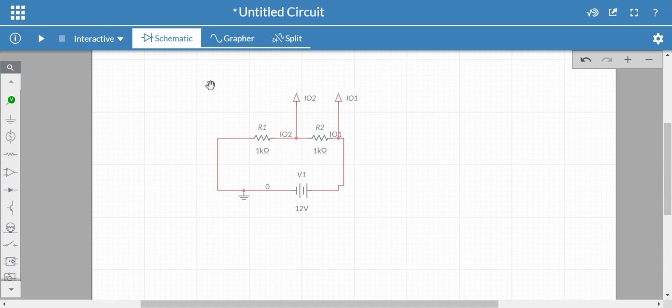Okay, one other function I found that makes life easier in Multisim is a junction in a wire. Right now all of your junctions are where the wires connect to the devices. So right here is a junction, and I can have a wire come from there and go somewhere, except it can't go to nowhere. And right here is a junction. Whoops, I'm hitting escape to get rid of that every time. Right here is a junction. If I don't like it, I can just hit escape.